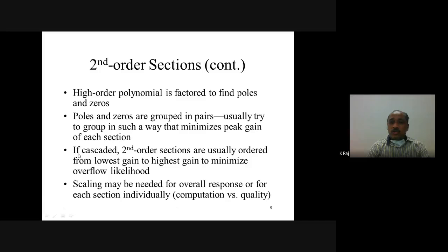And the next point is, if cascaded, then second order sections are usually ordered from lowest gain to highest gain. And what will be the effect? It will minimize the overflow likelihood. And scaling may be needed for overall response or for each section individually.